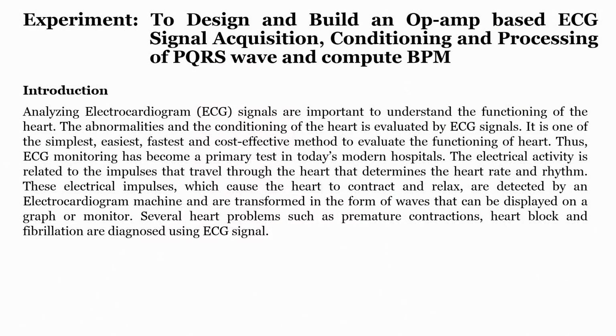So, in our case we are going to design and build an op amp based ECG signal acquisition, conditioning and processing of the PQRS wave and compute BPM. So, the whole idea is that we will be acquiring the ECG signal and extracting the QRS out of it, and we will calculate how many QRS peaks we are getting in a minute, which gives us the BPM.